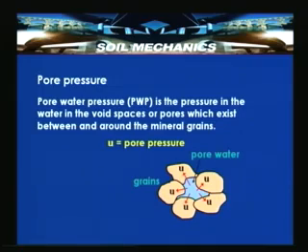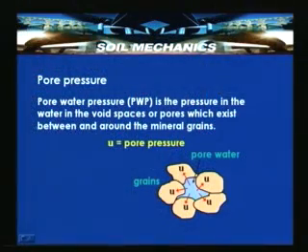Now, having introduced the total stress, it is required for us to understand and define what is meant by pore water pressure. We have discussed that the wide spaces which exist between the solid grains are called voids or pore spaces. If these pore spaces are filled with water, then water exerts pressure in all directions within the solid grains. So, the pore water pressure, designated as PWP or with a small letter u, is the pressure in the water in the void spaces or pores which exist between and around the mineral grains.